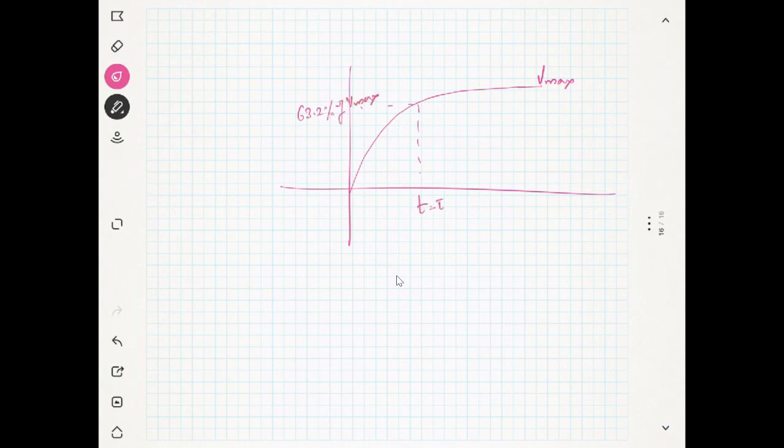Then this is time t equal to time constant, which we will see later. The time constant applies to both charging and discharging, and both are the same. How much change is there? Starting from 0, the change is 63.2 percent, not 36.